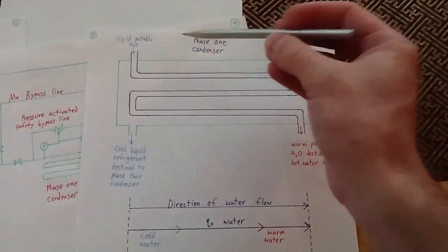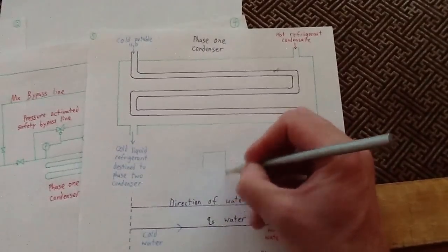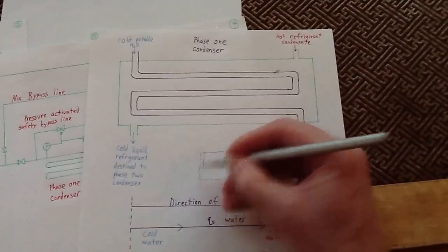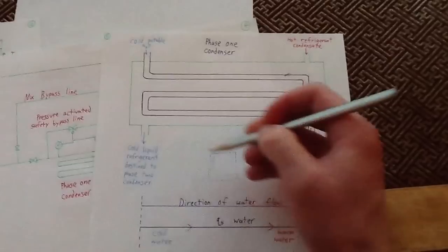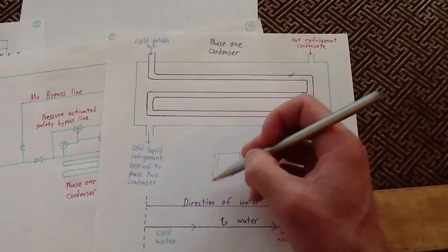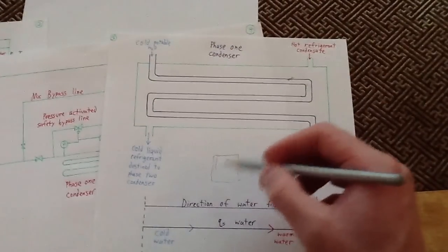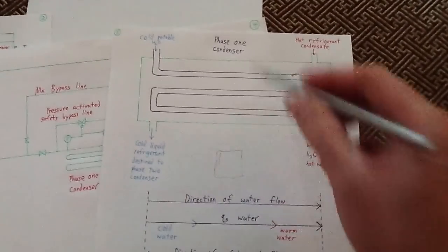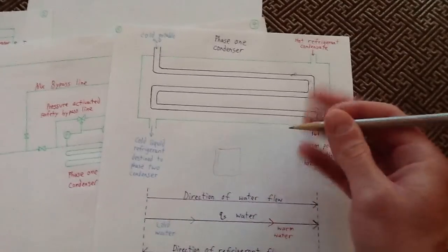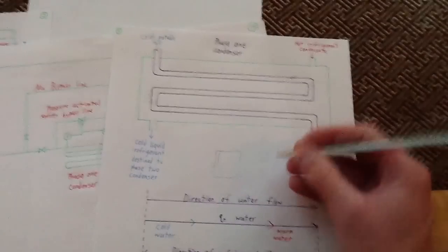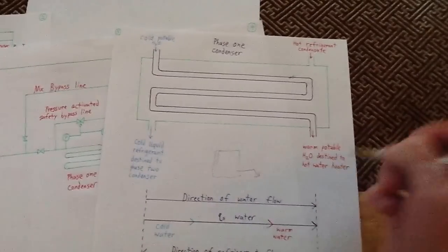But what you could also do in an ordinary house is have a large hot water tank here, in a closed cycle. It's going to collect in this water tank, and then it's going to take water at its coolest point and circulate it back through here, and it's just going to continue circulating water until it gets warmer and warmer each time it goes through the condenser. And then as there is demand for water, your dishwasher, somebody takes a shower, that's when it's going to draw water off there and send it to your hot water heater.